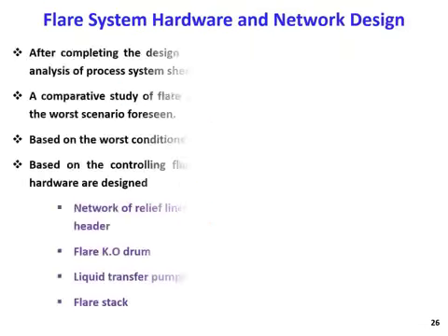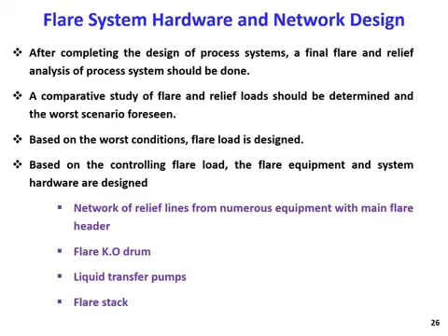Then, some additional information about designing the flare system. Once we consider all this equipment, the pressure set, the maximum capacity, and the worst scenario, we can do an analysis that we call the final flare and relief analysis, which has to be conducted to make sure that we respected all the safety aspects.